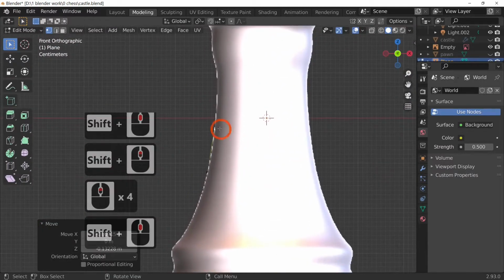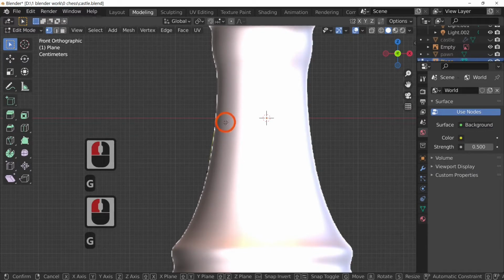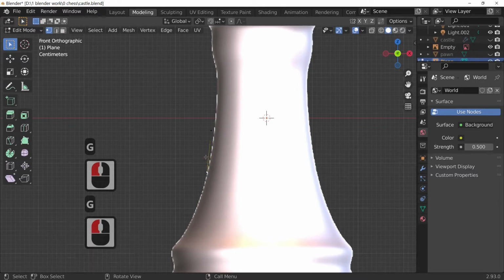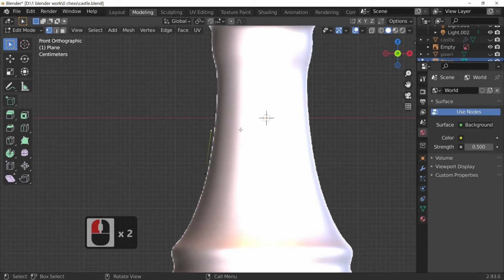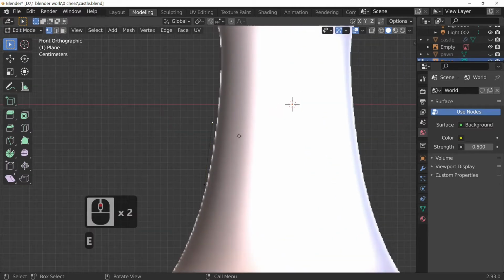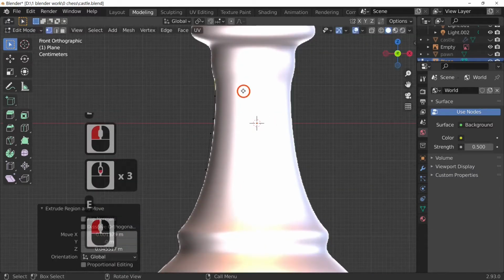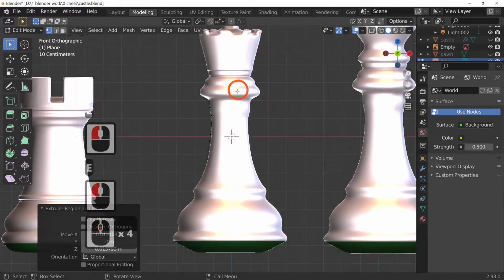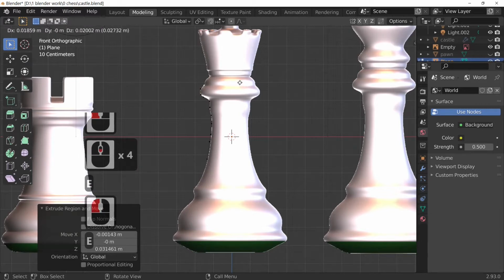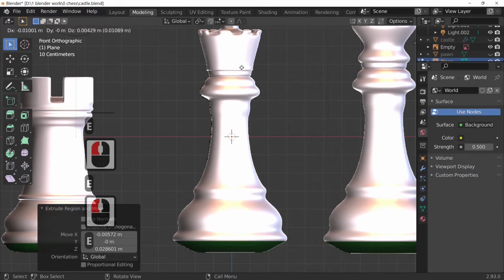And we're going to grow these points, just making it easier to see. I'm going to move them slightly onto the grey just to make it easier to show you when I'm making this. So I'm just going to extrude like so, and follow this line roughly round: E, and then I'm moving the extruded part. This is quite a quick way of building a model, and I'll show you how we're going to use the spin tool shortly to aid us in our design here.